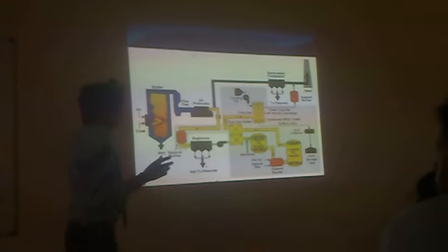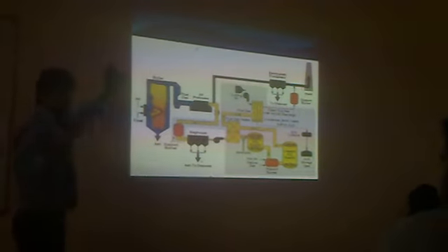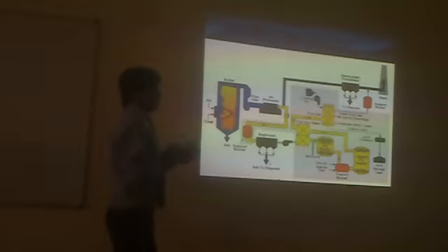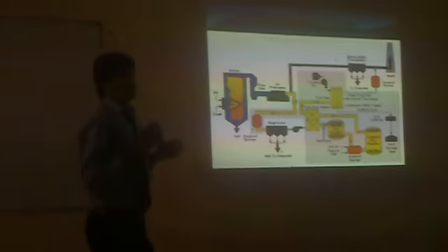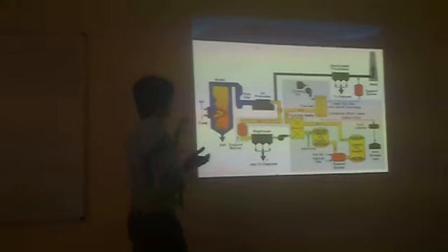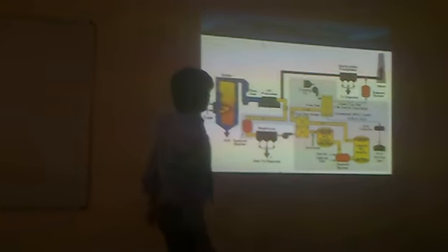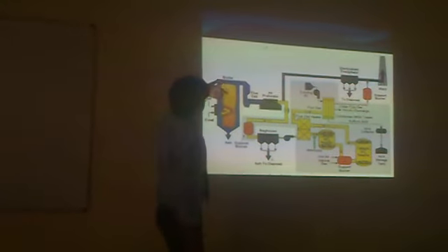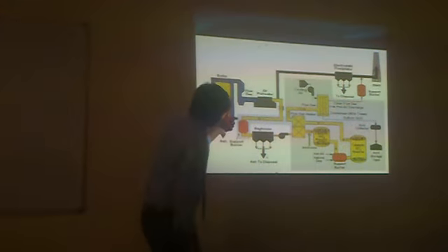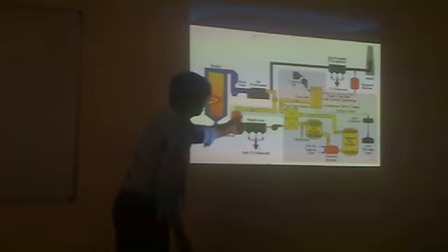If you send atmospheric air directly into the boiler, then the boiler's temperature is going to gradually go down and efficiency will decrease from 65% to 55 or 50%. So the air preheater is required. Now the flue gases come to the air preheater and then go to the support burners and baghouse.